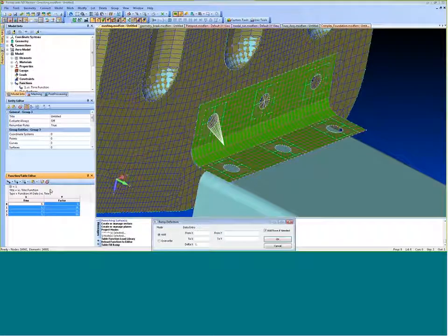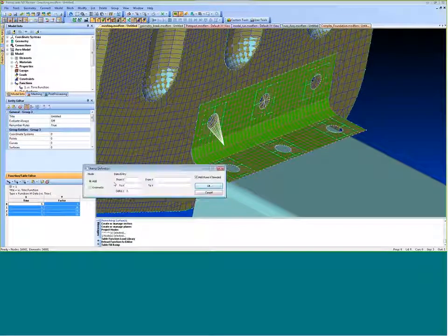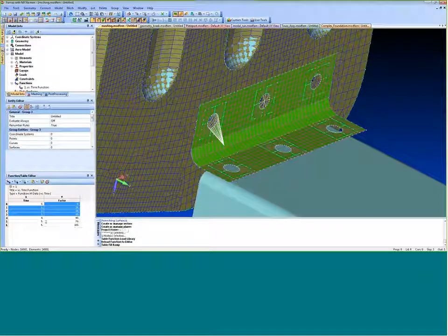If I right-click and do ramp, this ramp definition window is going to pop up. I can either overwrite my existing data or add to it, and say how I want to ramp it. We originally went from 0 to 3, so I'll say 4 to 6, going by 1. We originally already ramped it from 0 to 30, so I'll say going from 40 to 100. I want to add rows, add rows, and now there we go. We've edited our table and changed the ramp to whatever we want. And then again, you can save, et cetera.